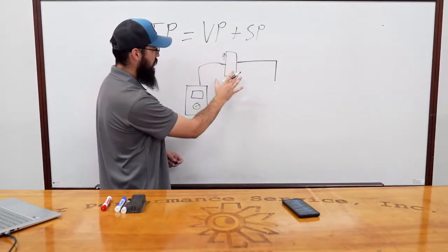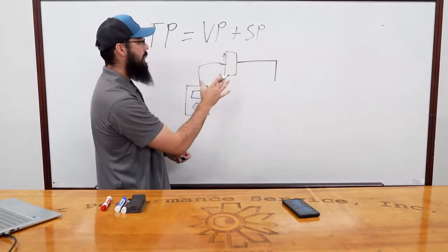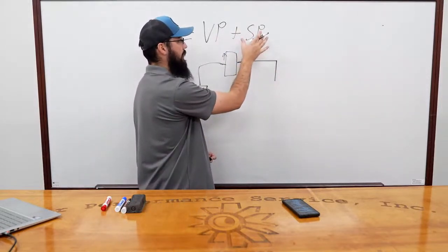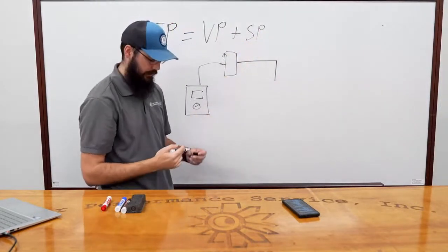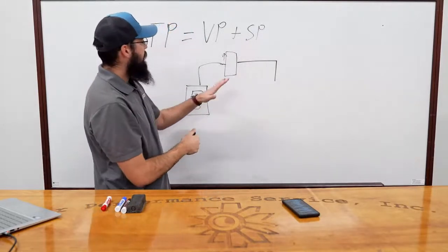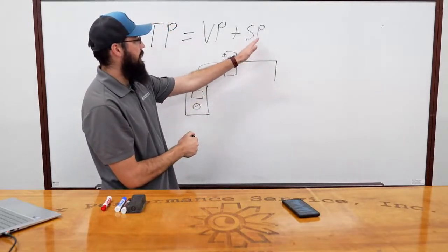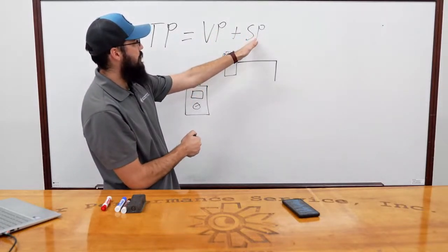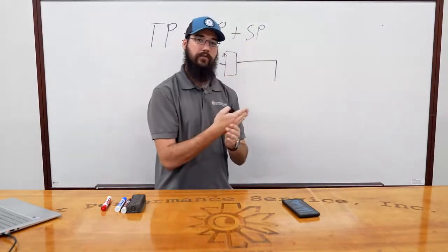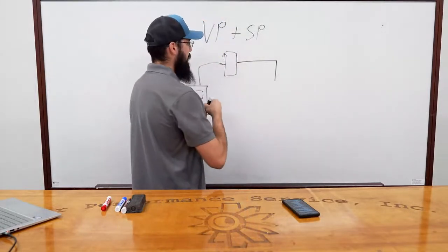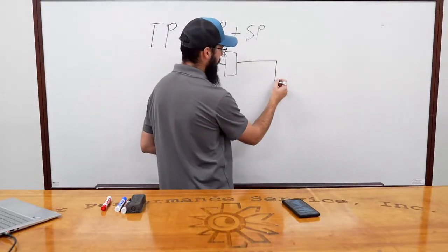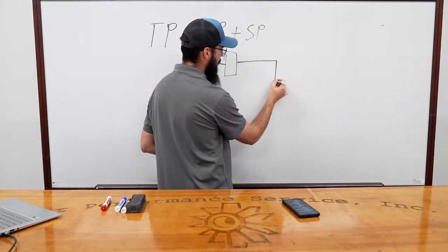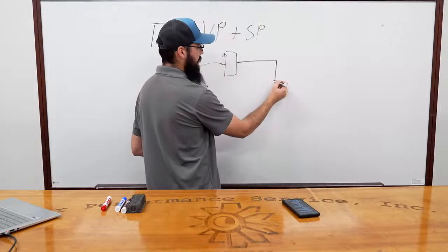And so what you're trying to do here is you can read two of these pressures with it. The one we really care about is static pressure in today's conversation. So what's important is, how do we get one from the other? We have to measure static by reading away from the airflow. So in this particular case, let's say that our pickup point was down here in the tip. So this is where we've got a hole.